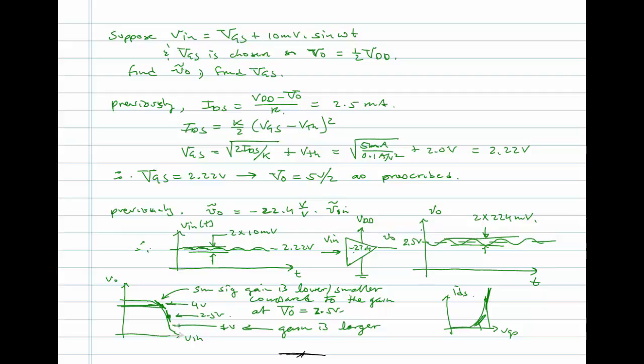So operating down here at 1 volt output voltage, where you're running at a higher current, would actually give you a greater gain. However, you're closer to bottoming out. Right? So you have a limited output voltage range before the amplifier clips, as we might call it. It clips low or it clips high. And so, although you can get more gain there, you can't have as much of a signal swing in the output. So you're better off oftentimes having it more near the center, where we have chosen it to be there at half of VDD.